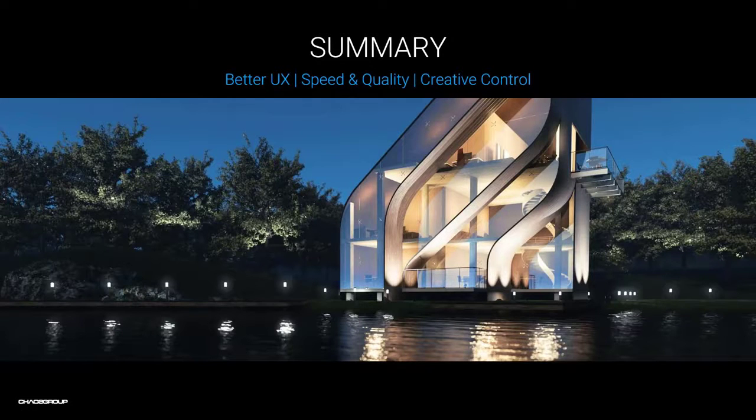Okay, with its simplified UI, V-Ray for Revit is easy to learn, easy to use, and easy to navigate. It offers different options for environment lighting. You can use the sun position from Revit or use dome light and create a picturesque background for your images. In version 3.7, you can finally change the gray color that appears on the horizon line.